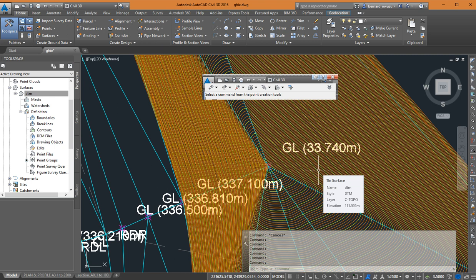Please, are you okay? But at a point it rises up, but I think the minimum, we can assume that, let's say the minimum elevation is 200, for example. So we are going to tell it that any value that it sees below 200 meters, it should forget, it should not use it. Though the point is there, we have not edited the point, you will see the point, but it should not use that point in building the surface. Please, are we okay? Any question?